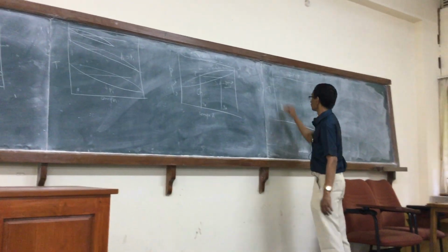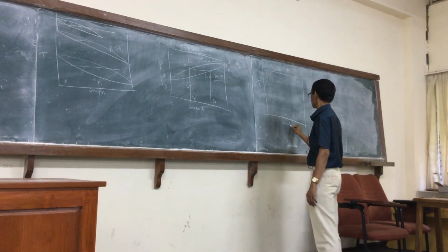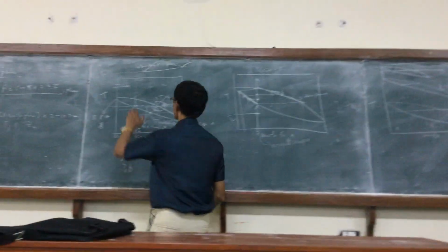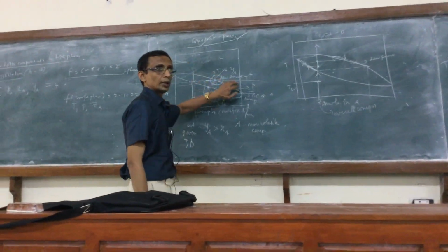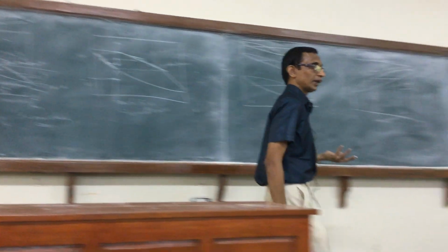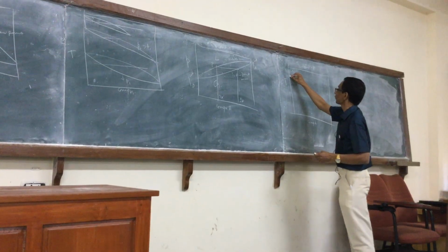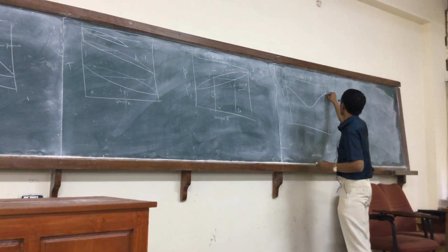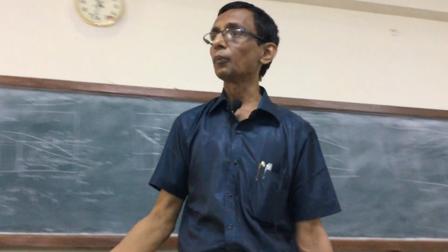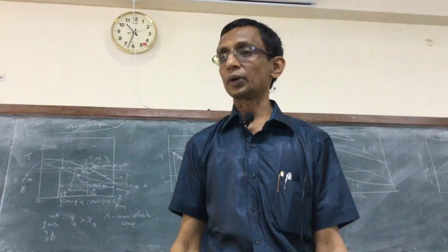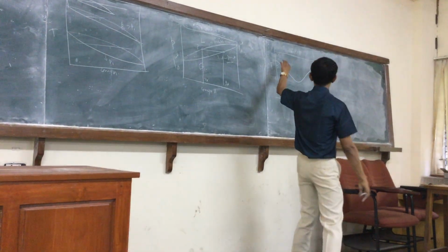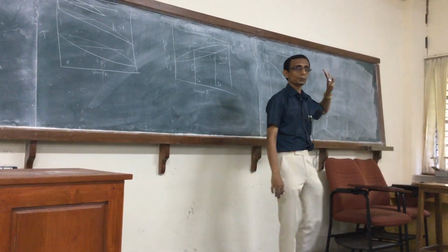Now the temperature versus composition, let's say, of A, and again the dew point and the bubble point. Now you can clearly see that here both the T versus X and T versus Y are monotonically decreasing. Now in the case of an azeotrope, let me first plot the T versus Y. You undergo, let's say, either a minimum or a maximum. Based on that, we characterize the azeotrope as minimum boiling. This is again about terminology you should be very clear. Minimum boiling means that the T versus composition will undergo a minimum at fixed pressure.